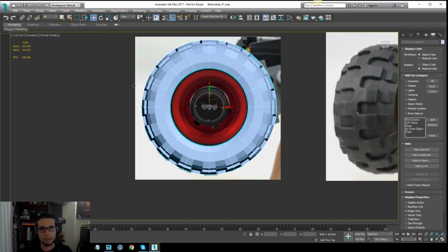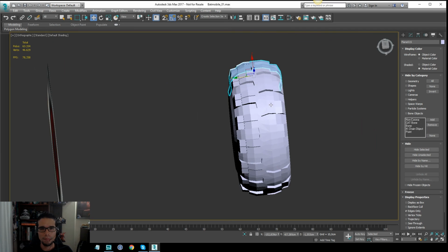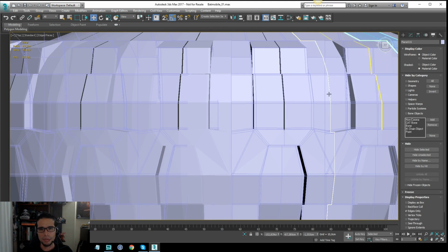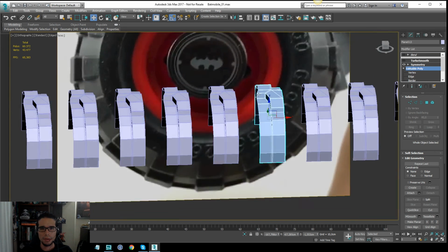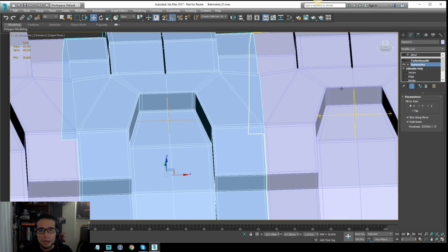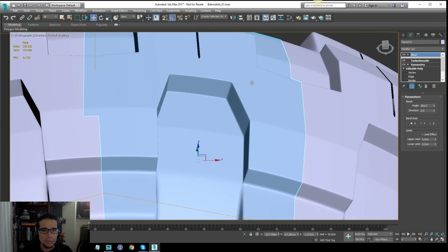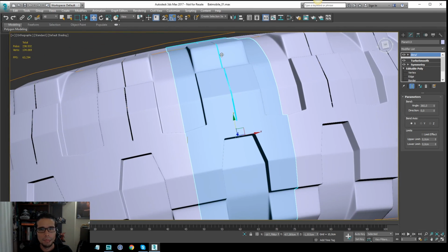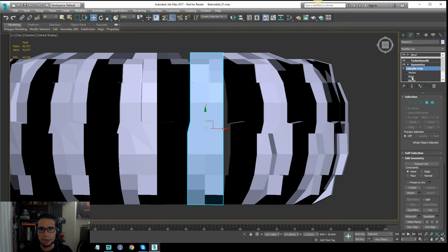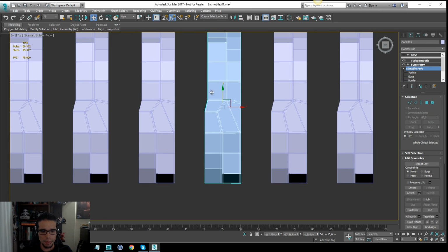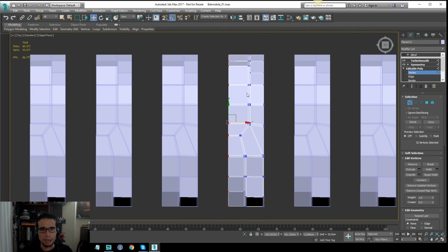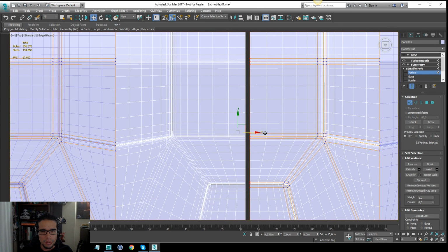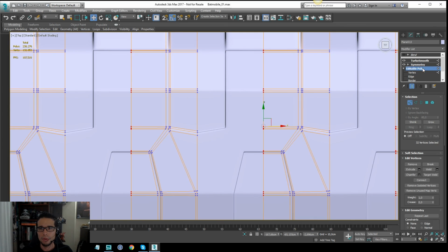Let's even make this more precise. Okay, this is almost exactly what I need. I'm having an issue here, because I have deleted half of the object. Remember, I have the symmetry here, and the turbosmooth, and then the vent. Let's see how it looks. Okay, so the issue in this part is just because when I put all this by this part, I forgot to move all these to the axis. All these things should be on one axis, because the symmetry will affect all of them, and that is it. They need to be exactly on the same axis to avoid this problem.